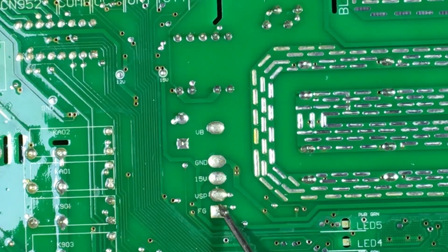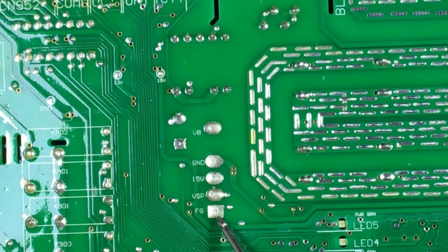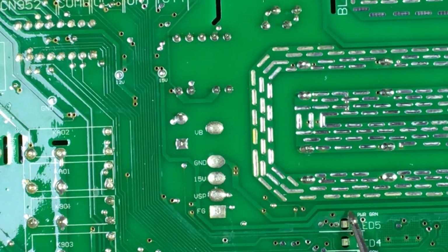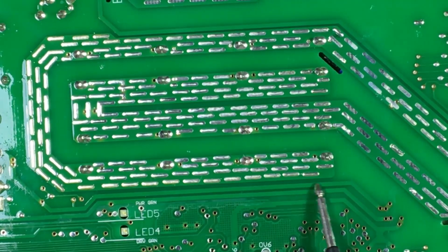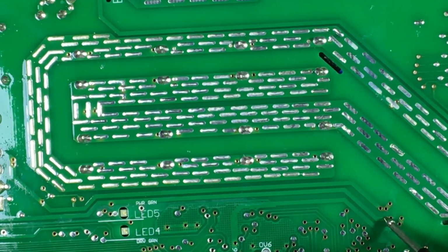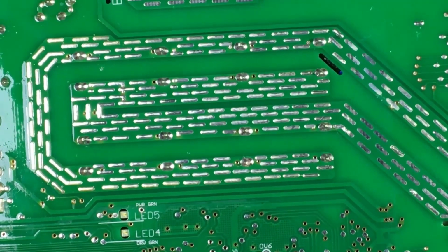This is the fan inverter connection socket. We will talk about that later. And notice that these 15 volts follow a path. I went off the camera, sorry. They follow a path and reach these points. These points are for transfers. Through these perforations in the board, the voltage is allowed to pass to the other side of the board when they are double-sided base plates.